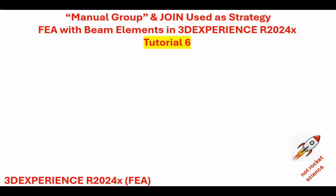And now I would like to show you a different way of handling that, a different strategy, which is based on joining the whole thing. However, because you cannot put forces and boundary conditions directly on nodes in this program, you're going to create a group which has that node in it, and then apply the force on that group.